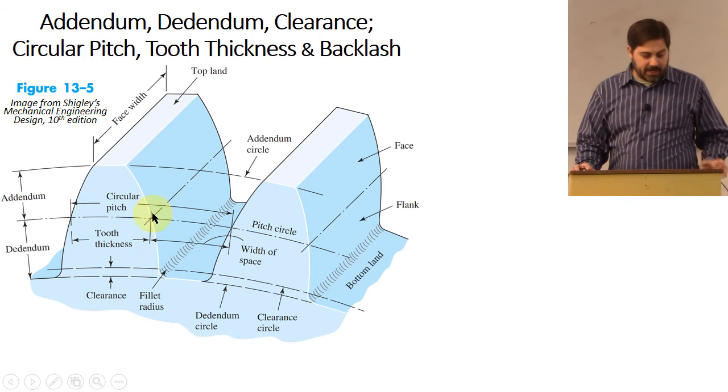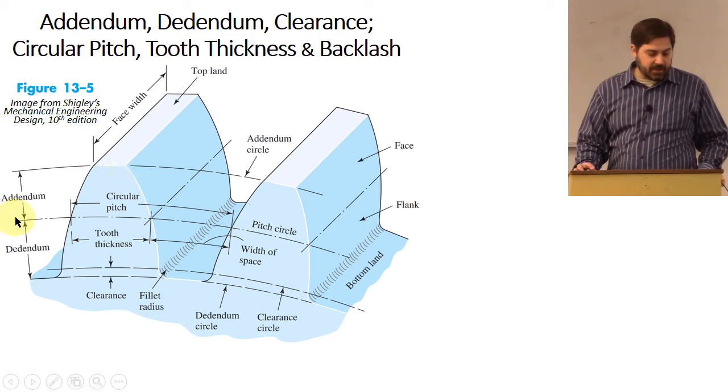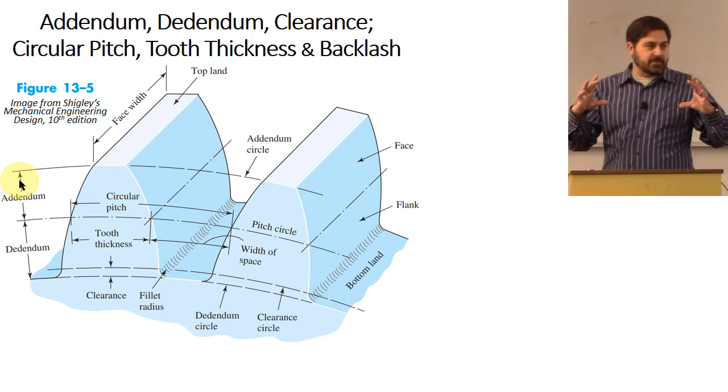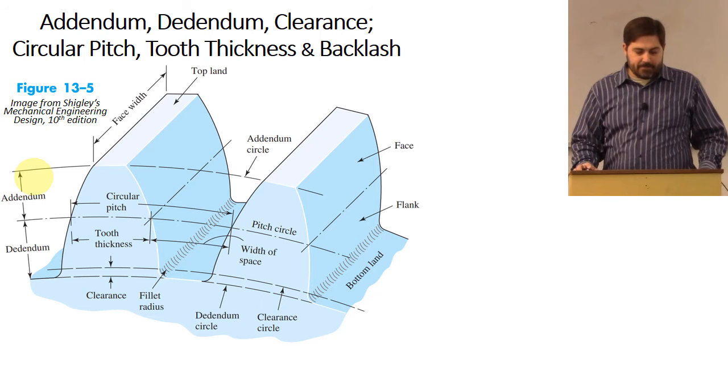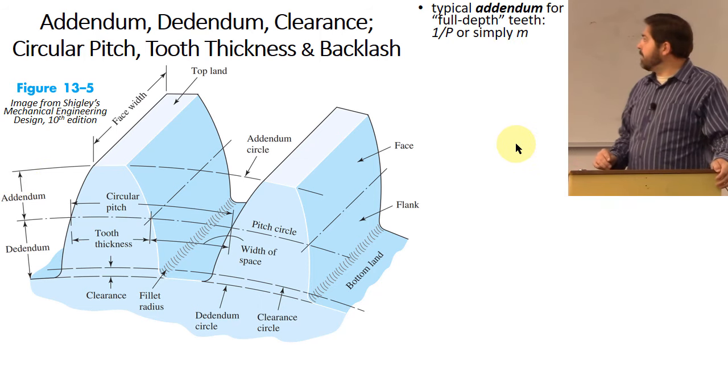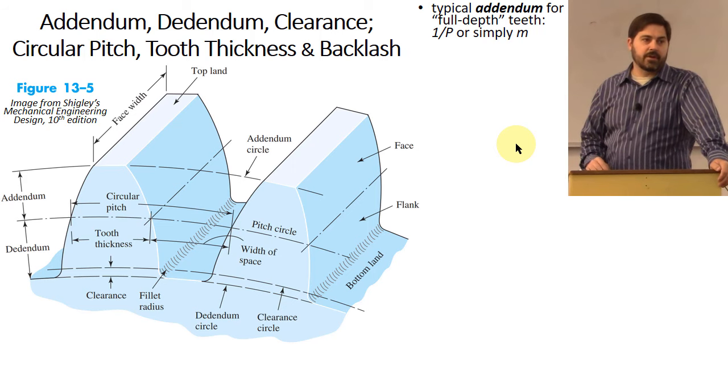What we do is we actually have the extents of where that involute curve goes to at the top end is basically cut off by something that is called an addendum circle, right? It's basically the outer diameter out to the limits of the teeth of these gears. And in standard gears, this addendum is set up by basically taking 1 over your diametral pitch P, right?